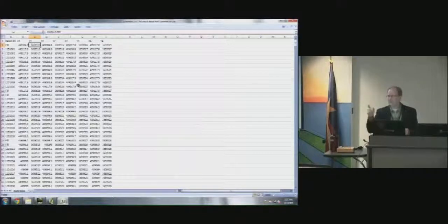Now, probably one of you in here, their field is located somewhere on the boundary between 2 UTM zones. So that's a very complicated situation where you have an experimental site that actually straddles 2 different UTM zones. So that might require a little bit of special treatment. But hopefully none of you are in that category.